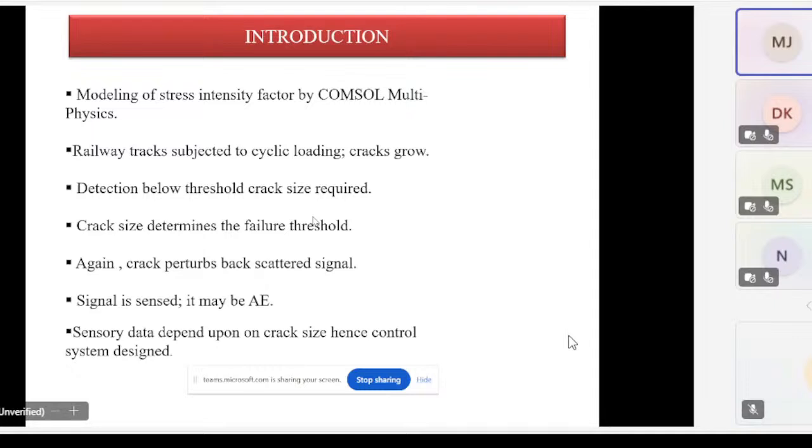Once the acoustic emission goes there and comes back, suppose it hits here, and suppose at the front of the engine I have a sensor. Once it comes back, this is the normal time, one cycle time of reflection. If there is any crack, then there will be a scattered reflection, which means the intensity will be lowered in the back propagation.